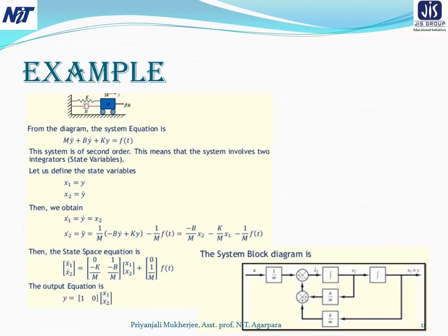So in this way we can describe the system by a set of first order differential equations, and then we can represent it diagrammatically by using the integrators, the summing points, and the constant multipliers, and we can form the block diagram of the system.